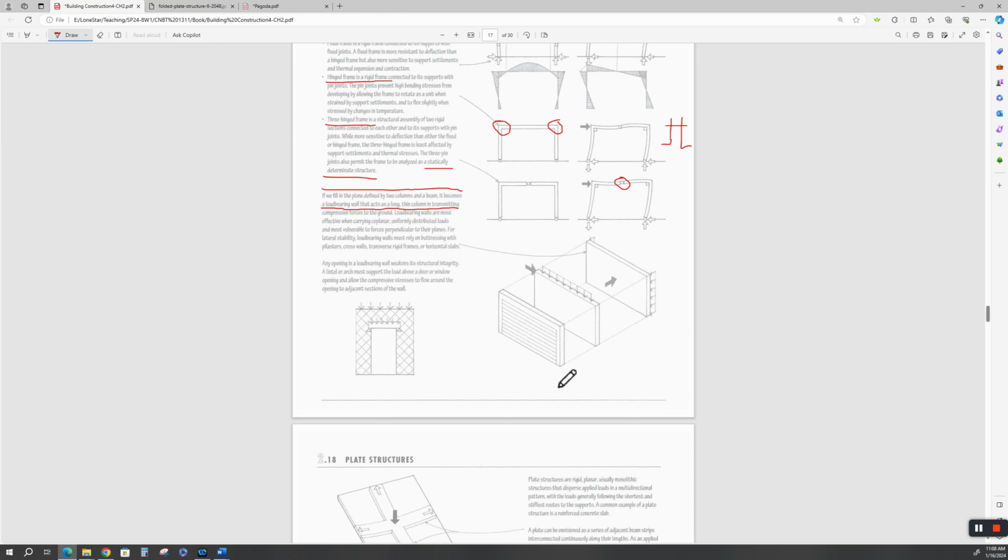And you see that as a shear wall in tall buildings and in apartment complexes where you may have wood framing, but you'll have a center concrete column where the stairs are that go up through it, and they'd use that as the shear wall for the whole structure, much the way the pagoda center pole works. Very rigid wall, but it's not meant to snake dance like the pagoda.